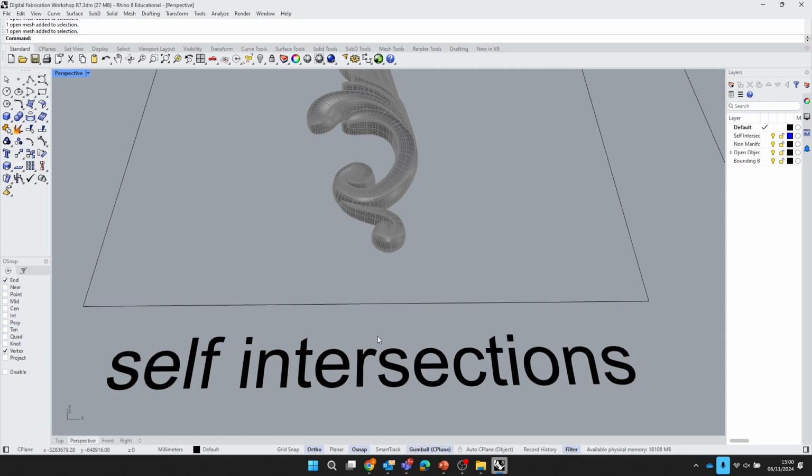It's basically turning itself inside out in some places. And what happens in that case is it doesn't know what side you want to print, because it has to be one clean, watertight object to 3D print something, yeah? Whereas if something then goes inside out, inside itself, it's like, is this the inside or is it the outside? I don't know. What do I do? And the machine will glitch and cause errors. And that's why you get a lot of failed parts on the printers.